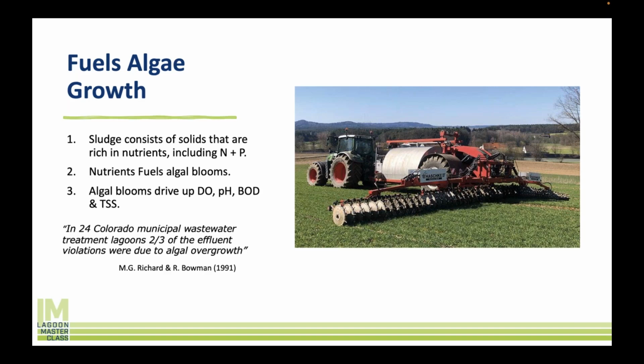they can also be helpful in growing algae. So I see this constantly where we have a lagoon system that has a really acute algae problem. And we ask them, hey, have you measured your sludge? Do you know how much sludge you've got? Right? Nine times out of 10, they have too much sludge, and that is fueling algae growth. Not only because of the nutrients, but because it also makes the lagoon shallower. And because it makes it shallower, it makes it easier for algae to form. So this is a big, big issue.